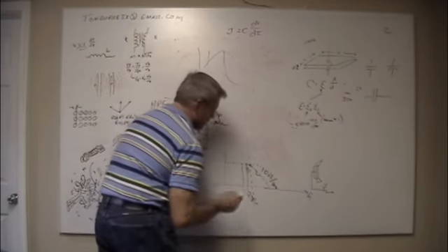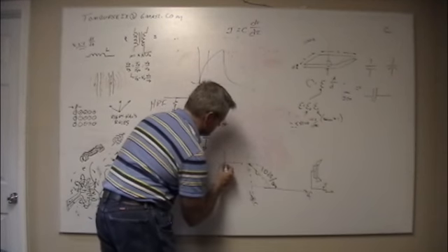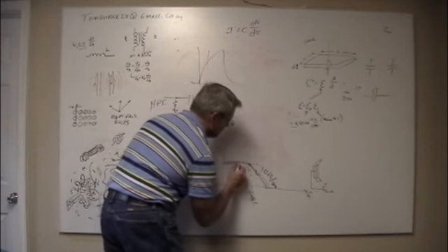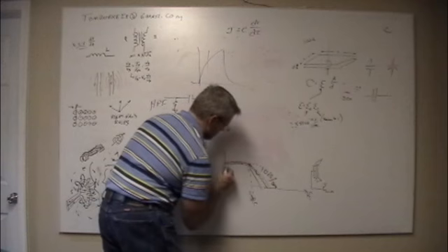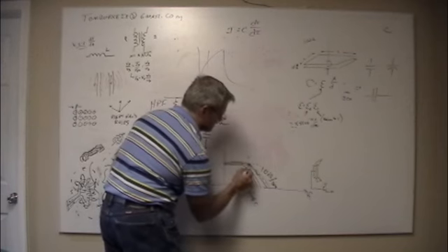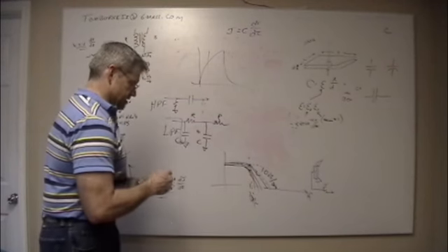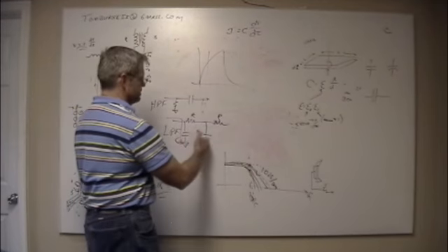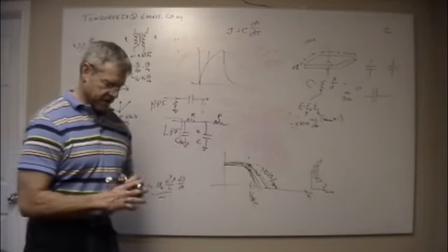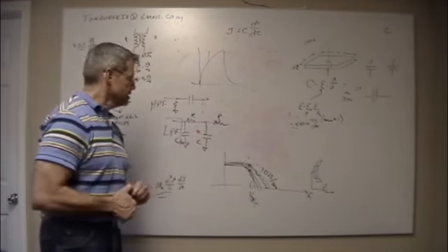Yeah, okay. But what you see, well actually, so F sub C still stays here. What you see is a thing that goes like that, and then to get there, it starts a little bit earlier, but that 3 dB point stays in the same spot. It just gets sharper and sharper. But to do anything realistic with this, it takes so many R's and C's that it's not worth the effort. You want to get into active components and use active filters that amplify the effects.